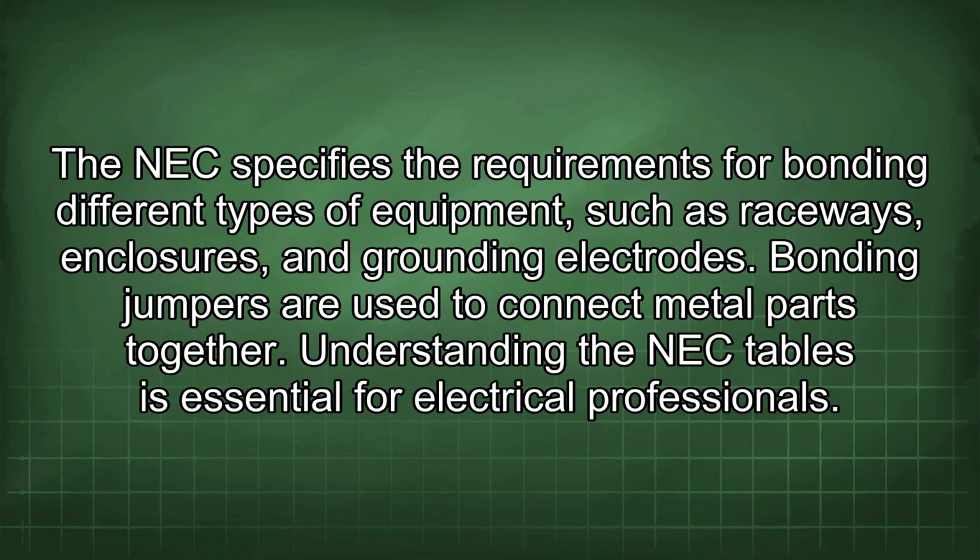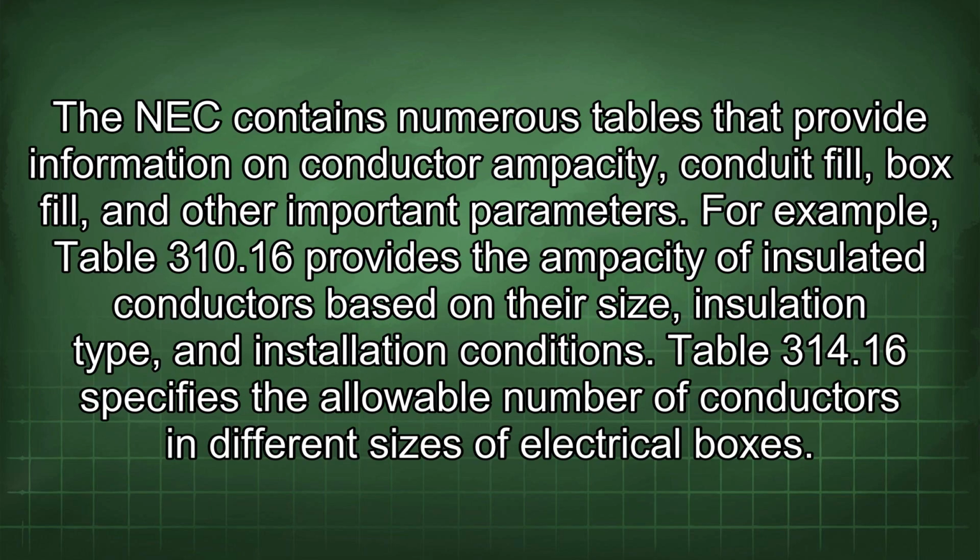Understanding the NEC tables is essential for electrical professionals. The NEC contains numerous tables that provide information on conductor ampacity, conduit fill, box fill, and other important parameters. For example, Table 310.16 provides the ampacity of insulated conductors based on their size, insulation type, and installation conditions.